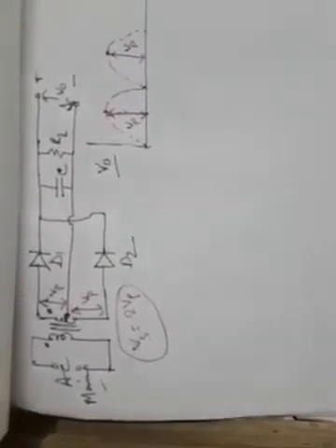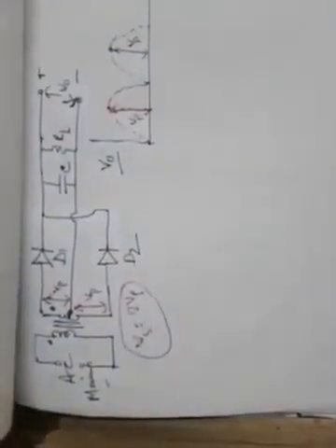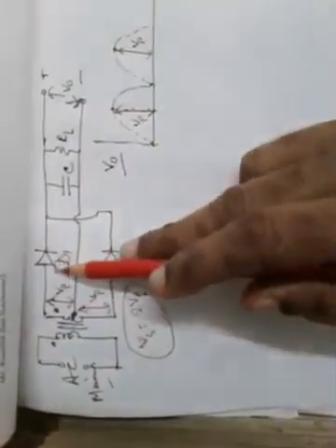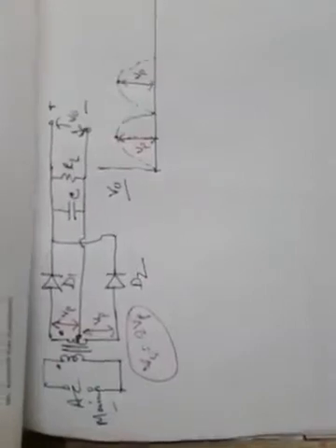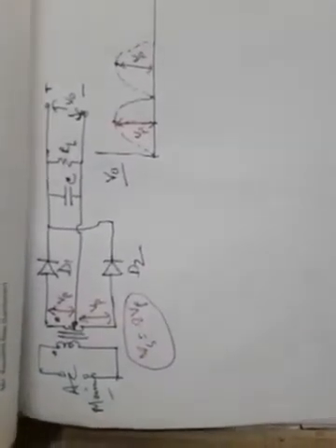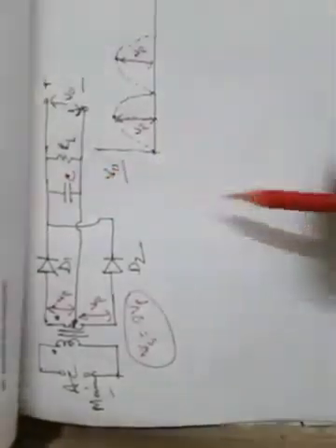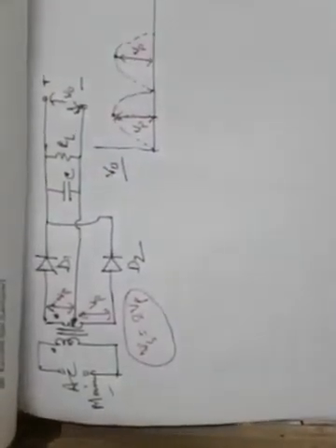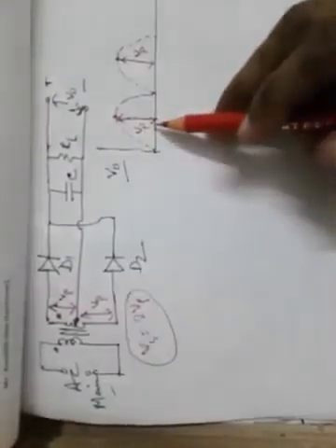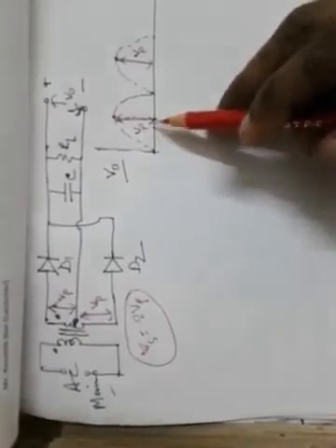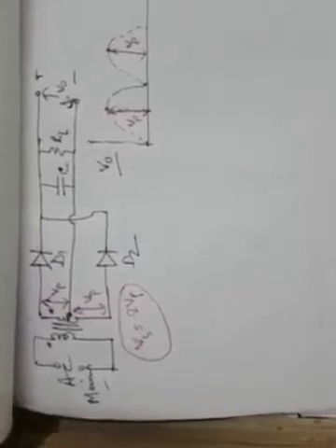Now when the filtering capacitor is used, if C is now connected with this, the voltage charges the capacitor. That means the voltage that is being passed from the input side to the output successively by these two diodes during the two half cycles will help this capacitor to charge up to a maximum value of this voltage, that means Vp. So C will be charged up to the peak value Vp. The charging current of the capacitor is always provided by the respective diodes.